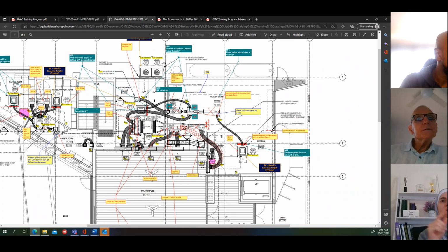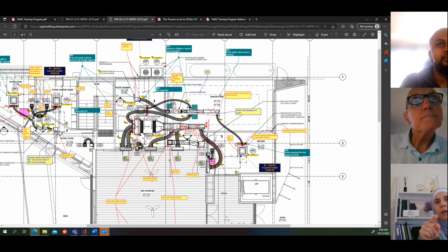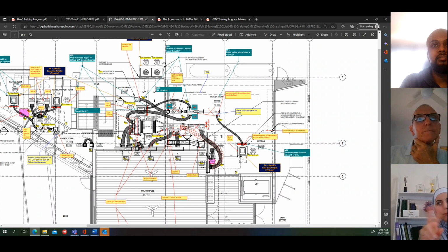Yeah. So if I'm using this workshop drawing for my calculations, I'd subtract 150 from both dimensions, width and height. But if I'm using that consultant drawing, I will use the size specified on the plan. I'm not going to consider anything about the insulation. That's right.